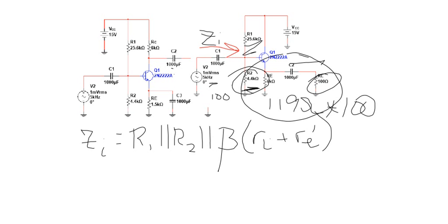So that's it. Even though this one has a gain of less than 1, having that bigger load resistance is going to increase the gain of the common emitter amplifier to more than make up for it.